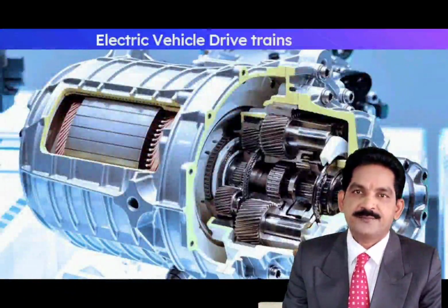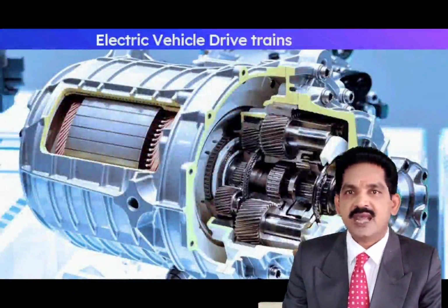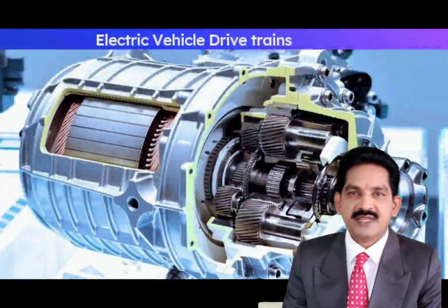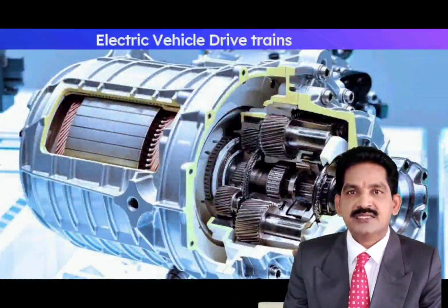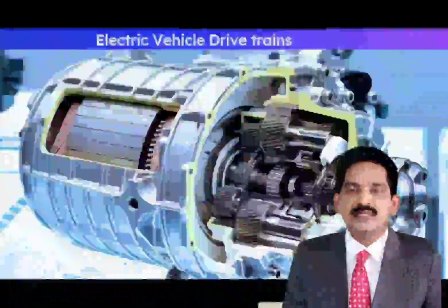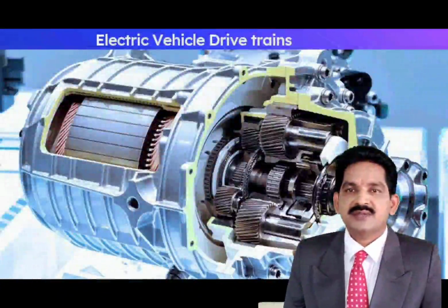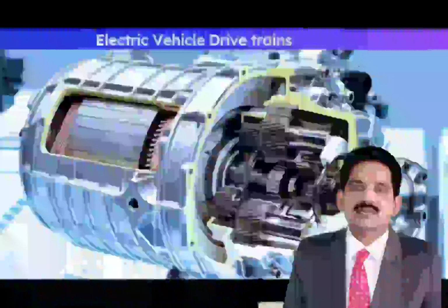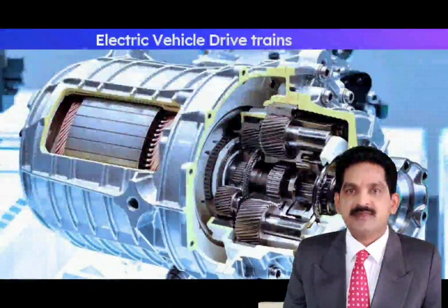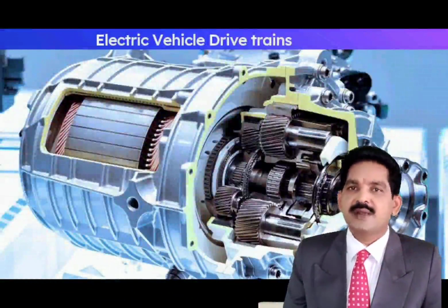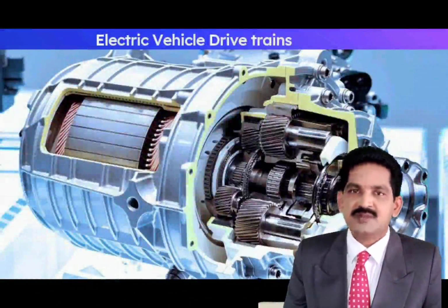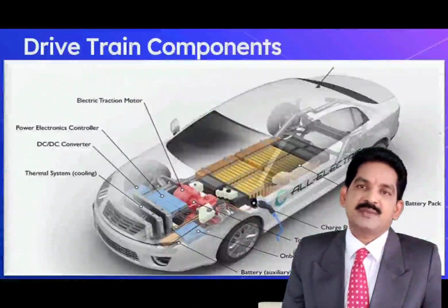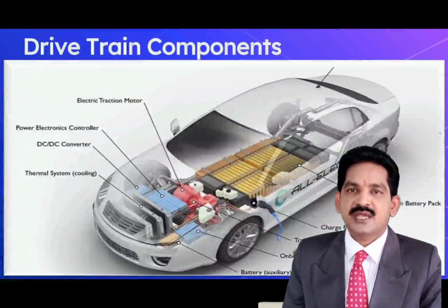components like straight and helical gears or planetary gear drive systems, which are typically tighter for electric vehicle components. The surface finish of gears also gains new importance as the noise emission of the drivetrain is critical in electric vehicles due to the silent electric motor. Hexagon has considerable experience in the development of powertrain components in both automotive and aerospace sectors and is well placed to support manufacturers throughout the development of electric vehicle drivetrains.